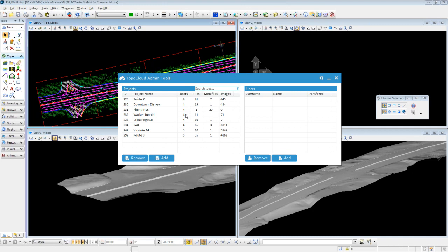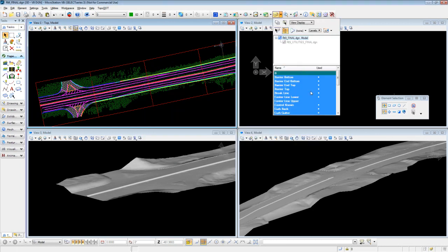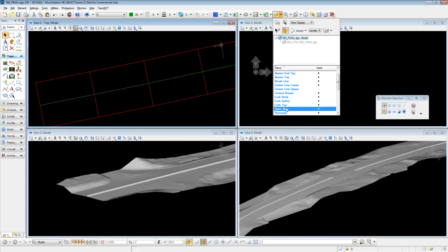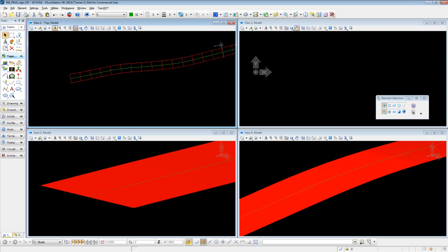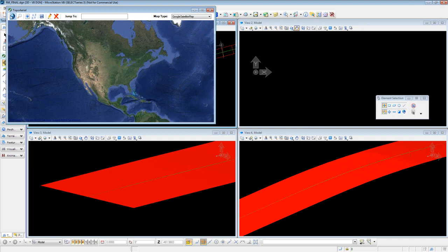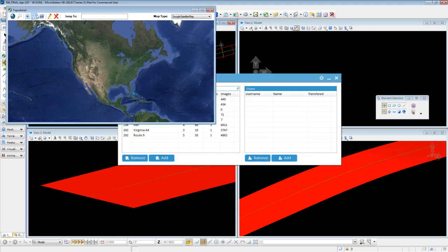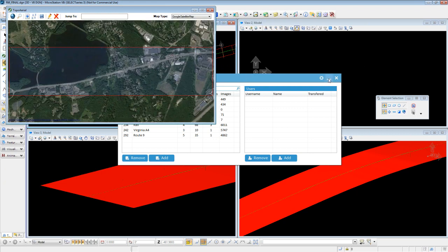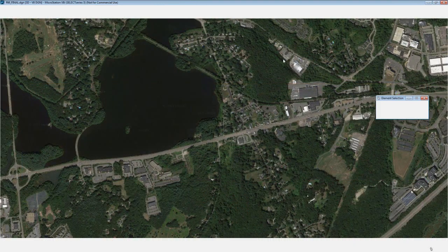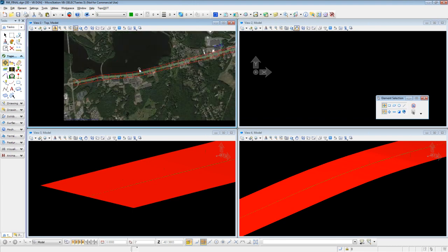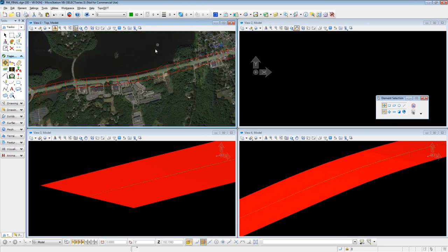If I can just interrupt at this point, just so everybody's clear, because Maddie just did a little bit of backtracking. This is still on the administrator end. So if Maddie, maybe turn off. The administrator is sitting there and has to have some TopoDOT experience. He turns everything off, and then he's set the alignment. He's looked at the tiles, and maybe pulling up a background will give these guys a feel. He's looked at it himself and said okay. He's loaded the aerial. So the administrator has done this. He's setting this up so it can be accessed in these small, simple tiles, and this is really key. Everybody here knows when you don't need data past, for example, that corridor, you don't need data past those tiles. It's worthless anyway.